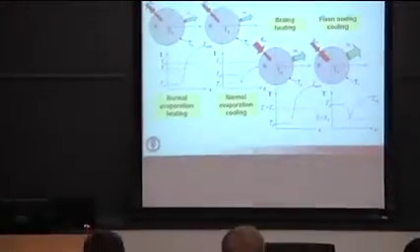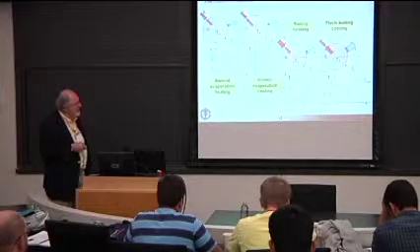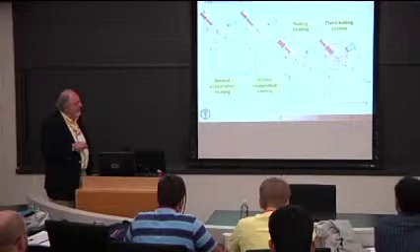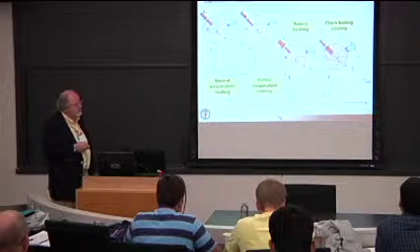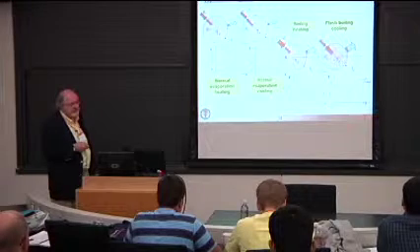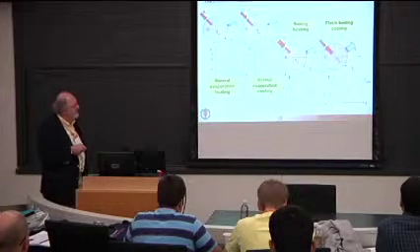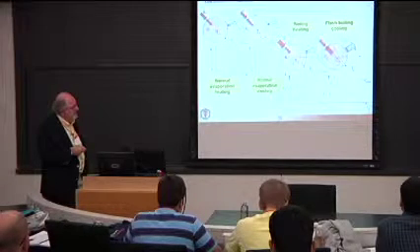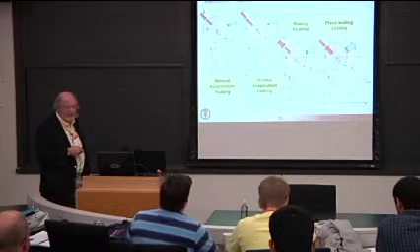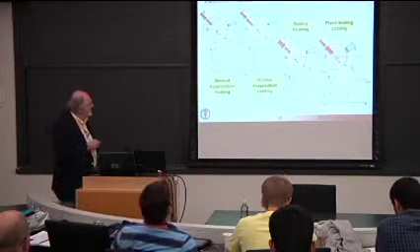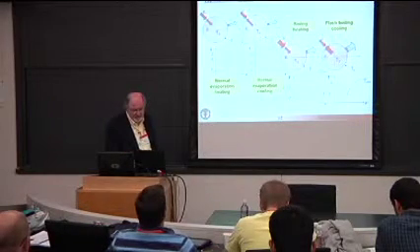So to prevent that, we have developed a model, and it's described in some of these papers, where we account for the boundary layer at the surface of the droplet. So we can actually have two temperatures. One is the droplet internal temperature, and the other is the droplet surface temperature. And then we can account for heat that is transferred from the environment to the drop, or heat that's transferred from the internals of the drop to the surface. And this allows you to then deal with these various regimes of vaporization.